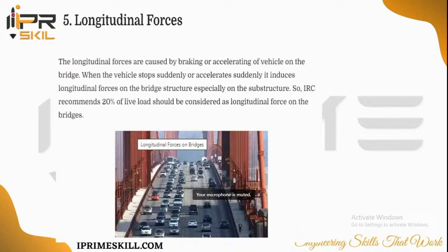Then these are the longitudinal forces on the bridge, which are caused by the braking and accelerating of the vehicle. When the vehicle stops suddenly, what happens? It induces longitudinal force on the bridge. So IRC recommends that 20% of the live load should be considered.